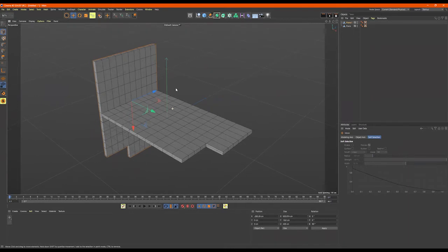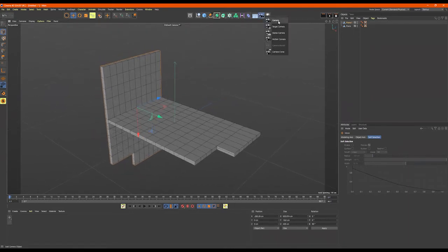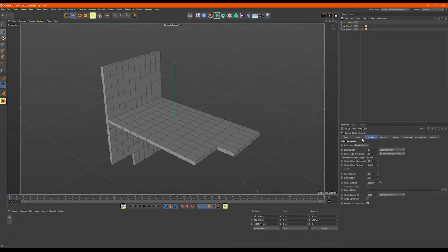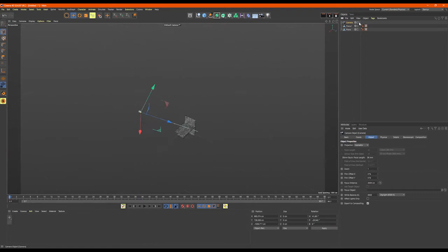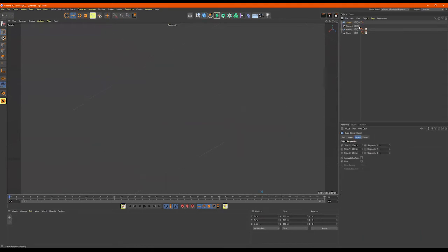And also one other thing I'll do, I'll set up the isometric camera, but well, I guess let's just do it now. We set up a camera, we click on it, and we go to the panel, the projection, go to isometric. So that's our isometric camera. If we want to get inside, we click on this. Get inside. And actually, let's just go ahead and lock this. Or let me get out of it for a second. I'm not sure what it's looking at exactly.